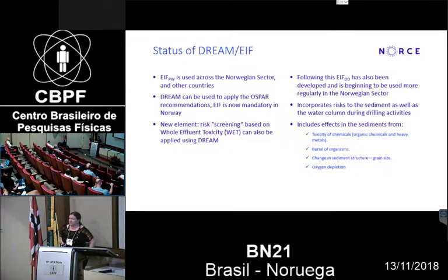We also have the possibility to run whole effluent toxicity because you have a lot of interactions with the chemicals down the well, which are not taken into account in the actual model. So part of the OSPAR recommendations was whole effluent toxicity. So then you assess the toxicity of what comes out as a whole effluent rather than on a component-based level. Sometimes it comes out more toxic than the individual components, and other times it comes out less toxic because of the way they all react together.